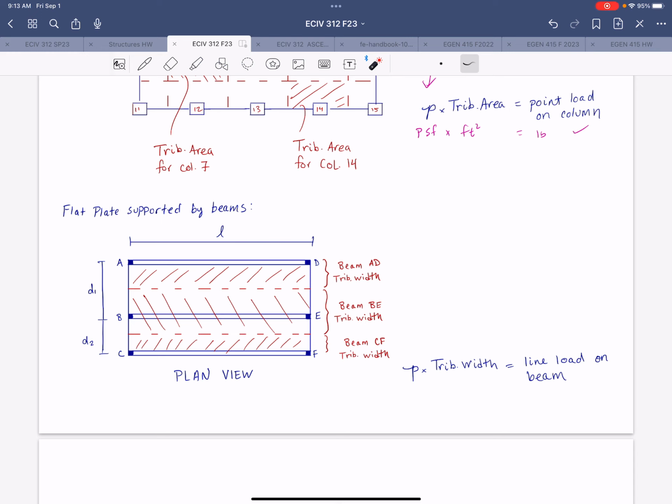So generally speaking, in practice, there's a rule of thumb used to gauge whether a floor system is one-way or two-way, and that's if the width to length of the area between supporting elements is above or below 2, I think is the cutoff that they use. So you can use that as an indicator, but there are other things you have to think about as well.